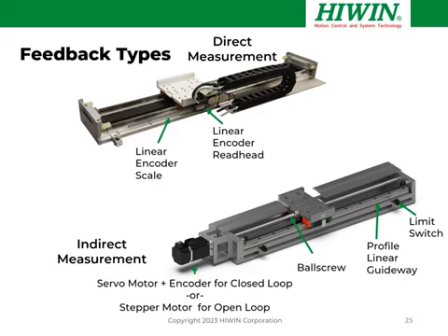A linear motor with a linear encoder is the highest performance solution. Your speed, your accuracy, your dynamic behavior will all be better, because you're measuring directly. So you would have a linear scale and a linear encoder read head mounted in direct measurement of the position of the payload. But again, you will still have ABI errors because that encoder read head is not exactly where your tool point is. So those deflections are still going to exist.